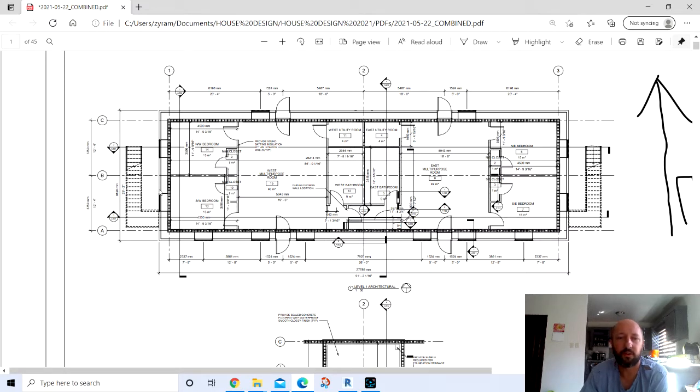By thermal bridge, I mean that's where your energy, your heat and cooling, escape the building. They're through the doors and windows because they are the least insulated part of your building shell. So really, reducing the quantity of windows and doors is the best way to go, as opposed to having a large quantity of southern facing solar windows.